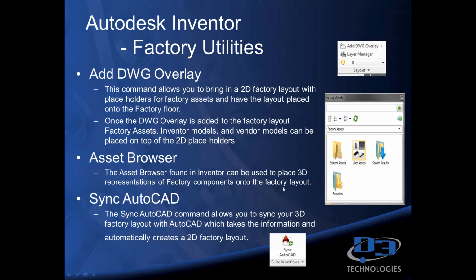Then we're going to have our asset browser. Very similar to the asset browser we saw in AutoCAD Architecture, we're going to have system assets and user assets. The only difference now is we're working with the 3D representation versus the 2D representation. So we're actually working with the 3D model. And similar to AutoCAD, when we are going from 2D to 3D, when we want to go from 3D to 2D, we have a sync AutoCAD command. This command allows you to sync your 3D model with AutoCAD and take that information and generate your 2D factory layout. So again, streamlining the process of going between the two software.